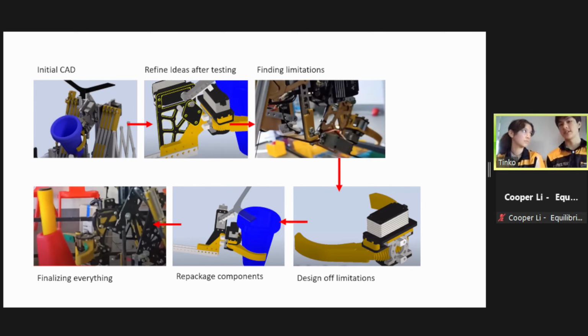Then, as you can see on the right, we built it in a cheaper material: 3mm MDF and zip ties, and we didn't do our wiring super properly. We just made it as quick as possible, did some quick testing, and found there are clearly some structural weaknesses in this component, so we need to make it stronger. We're also trying to reduce weight, but we decided to add some more structural cross bracing here and really think of a considered solution.